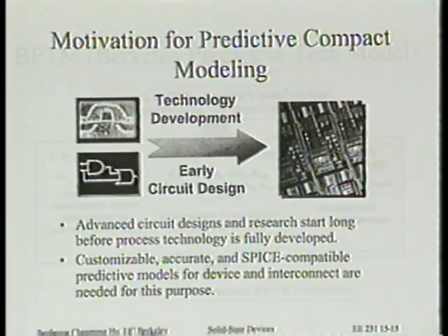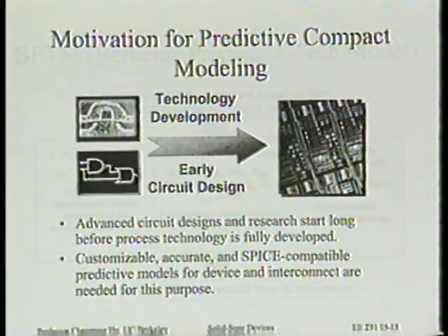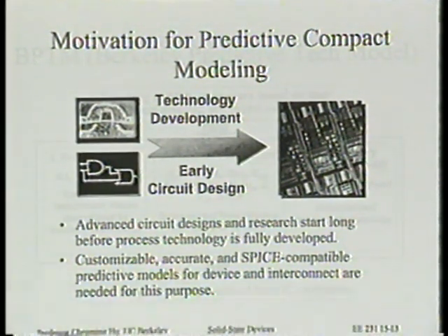For a long time, we've been saying that a model like BSIM has so much physics in it, one can use it in a predictive manner. And there are many ways to say how you use it. One is to say how to translate the physical variation data from the fab. Let's say we know the sigma of Tox. Then we immediately import that into the compact model. We automatically know the variation of the transistor characteristics. That's great, and I think most people accept that and do that now.